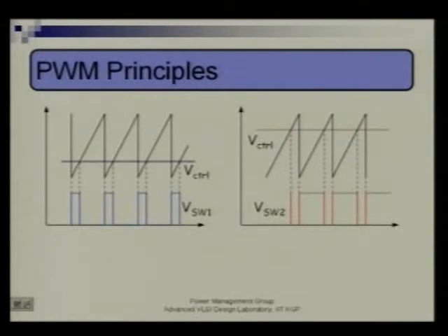Now we come to something called PWM, pulse width modulation. Why? Because PWM is the common technique used in generating the switching signal, the duty cycle signals that I have shown. There will be a ramp, which we call a sawtooth signal, and there will be something called a control voltage, VC, that I have marked in your compensator-plant diagram. So suppose in this PWM, this VC leads to a switching signal.